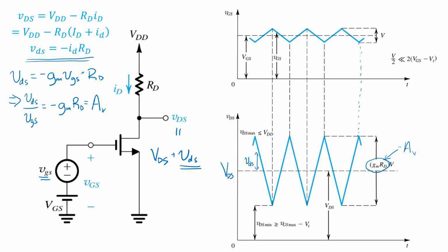So, again, this simplified linearized analysis is predicated on a couple of assumptions. The first we mentioned already is that the applied signals are small enough to keep the linear approximation valid, but we also have to make sure that the transistor remains in saturation mode throughout all these voltage excursions. So we first need to make sure that the peaks of the VDS waveform that we compute in this way are less than VDD.